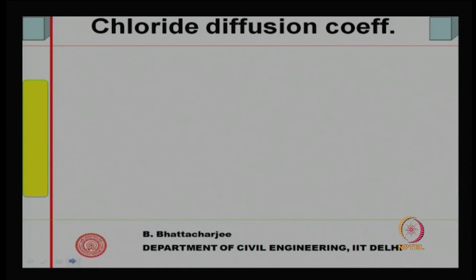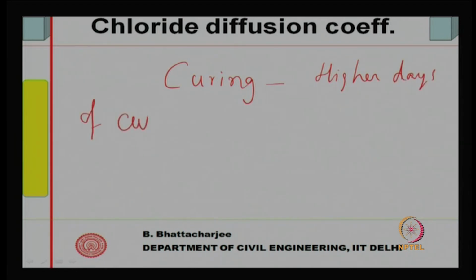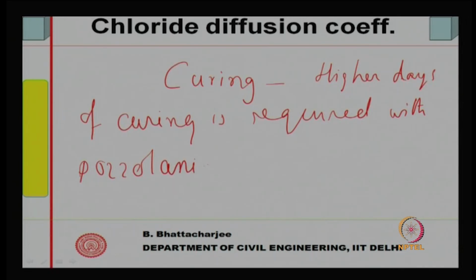Now, before we come to durability, I would just like to point out that curing is very important for mineral admixtures. You need higher days of curing with pozzolanic mineral admixtures, because their reaction itself is slow and sufficient lime must be produced before the pozzolanic reaction can be realized.